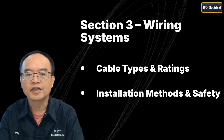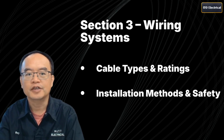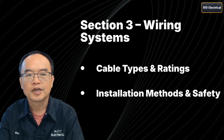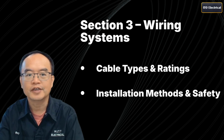Section 3 covers the selection and installation of cables. Here, you'll read about sizing conductors for load and voltage drop, choosing the right insulation for environmental conditions, and installing cables in walls, ceilings, or underground, so they're protected and easily identifiable.